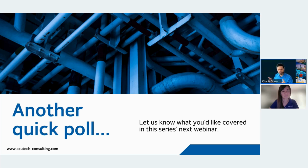But note that they need to overlap, right? You're testing the sensor with the logic solver, making sure that the sensor will trigger the function, and that valve can be bypassed or so. You don't want to stop your service. And you will test the logic solver with the valve, making sure that when the logic solver tells the valve to close, that valve will close. So in that way, you're testing sensors and valves at different times for whatever reason, but they have to overlap.